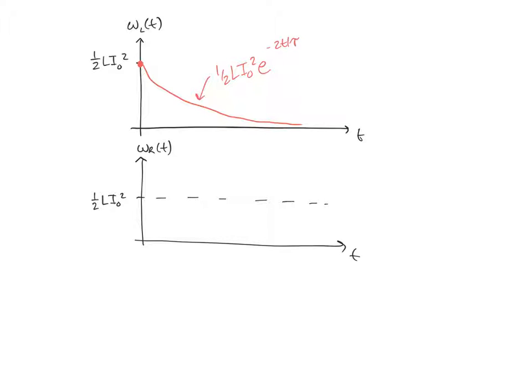If we look back at our theory for the decaying function of both voltage and current and compute the energy out of that. So the energy dissipated by the resistor, though, so the energy is being transferred from the inductor to the resistor, starts at 0, rises as an exponential function towards a final value of 1/2 L I squared. And that function is given as 1/2 L I squared times 1 minus e to the minus 2t over tau.